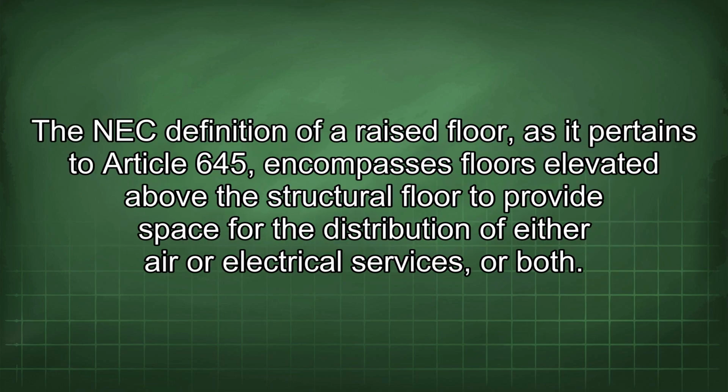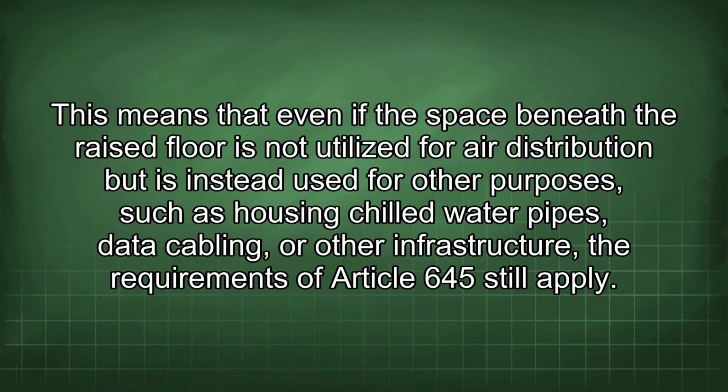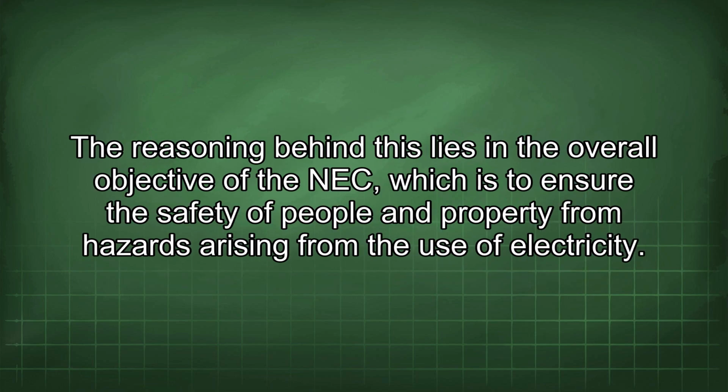The NEC definition of a raised floor, as it pertains to Article 645, encompasses floors elevated above the structural floor to provide space for the distribution of either air or electrical services, or both. This means that even if the space beneath the raised floor is not utilized for air distribution but is instead used for other purposes such as housing chilled water pipes, data cabling, or other infrastructure, the requirements of Article 645 still apply. The reasoning behind this lies in the overall objective of the NEC, which is to ensure the safety of people and property from hazards arising from the use of electricity.